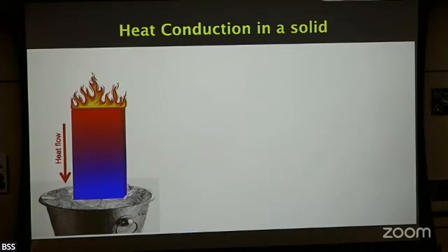Okay. So this is how you actually measure heat transport. You have your sample, preferably long, okay? And hopefully along this direction, there's no significant anisotropy. That's what we assume. And then you heat one side, so you put in constant heat. And at the bottom here, heat is constantly leaving. So you're in a non-equilibrium state, by no means in equilibrium, okay? This is the so-called steady state.